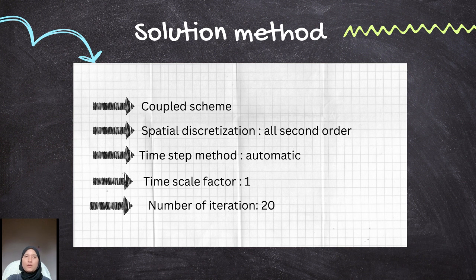And then the convergence criteria used for the simulation were the convergence of residual and the convergence of the drag coefficient. The drag coefficient itself represents the drag force experienced by the object or the flow field, and its convergence indicates a stable and consistent drag force value.